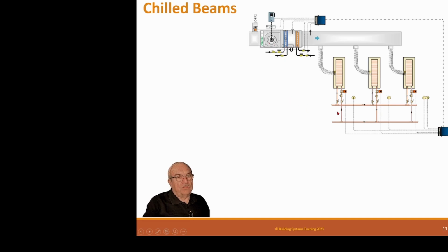It has a control system. It normally has 2 control systems. It has one on the fan coil unit, or air handling unit, and it has one down for the chill beams themselves. This unit basically is a fan and 2 coils, 2 valves to run it, outside air damper just like all those. And these have room sensors. And somewhere it must have at least one humidity sensor. And of course, it's got valves down on the boxes themselves, the chill beams themselves.